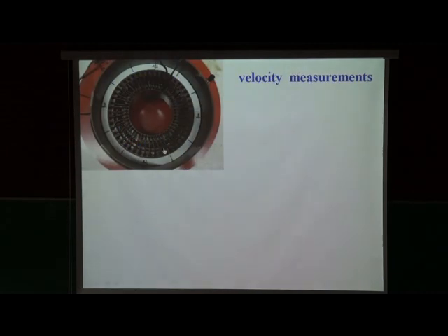And here you see the impact of such a field. Here we have a small ship, and you see that the ship is flowing with the flow, and the ship is a small part of plastic swimming on top of the ferrofluid. And switch it on again. So you see that you can excite a spontaneous flow by a rotating magnetic field. This is not possible with an alternating field. There you get only a viscosity reduction. Here, the reduction of the viscosity is so large that you get a spontaneous flow.